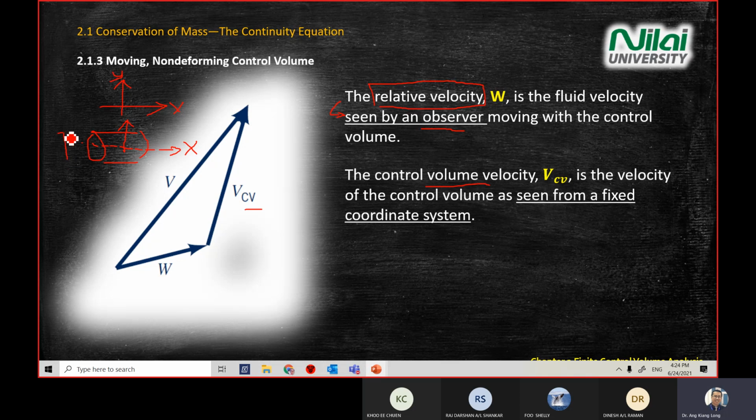And just to recap, when you deal with a pipe with non-uniform flow, you have a maximum velocity at the center, U max at the center, and you need to consider friction flow. Then at the wall there, velocity equals 0. If you don't understand what I'm talking about, why this one is 0 and why this one is U max, refer back to the previous derivation for pipe velocity.